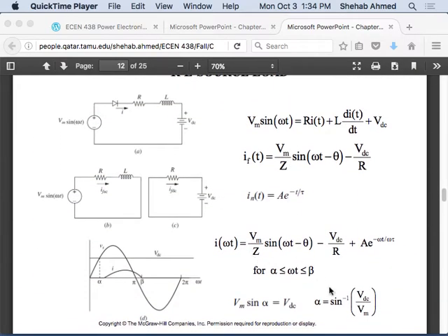Here, again, we know that the waveform of the current will be very similar. It's going to be a bit of a repetition, but bear with me. We write the voltage equation around the loop. We find that it's a first order differential equation with a forced response. Actually, this DC you can bring to the left, because the DC and the AC sources constitute your forced responses. I have two forced responses, and I have a natural response as well due to the first order differential equation.